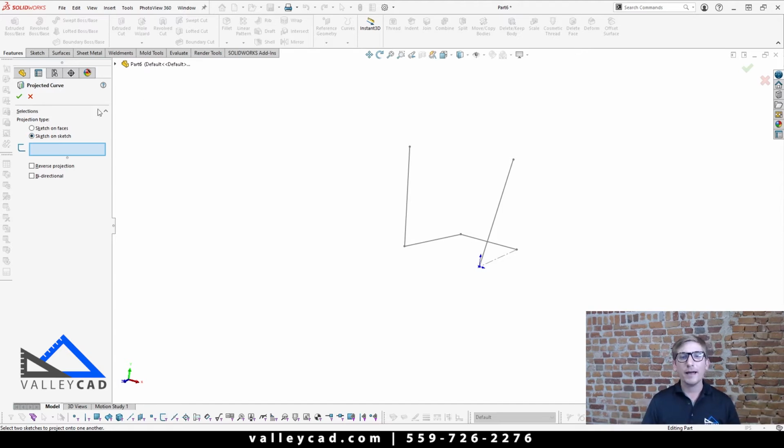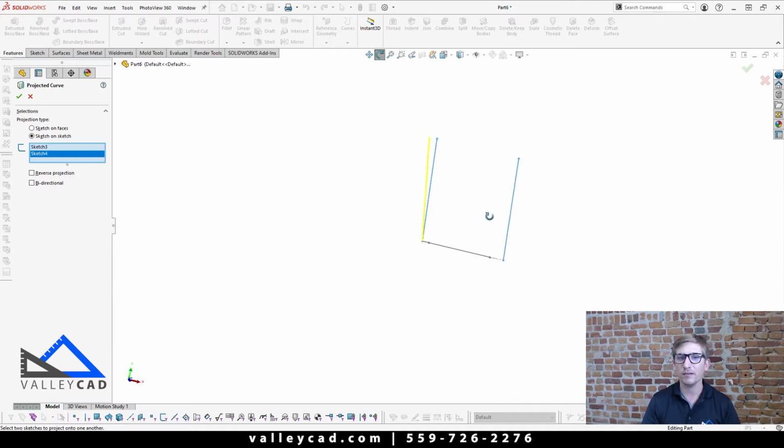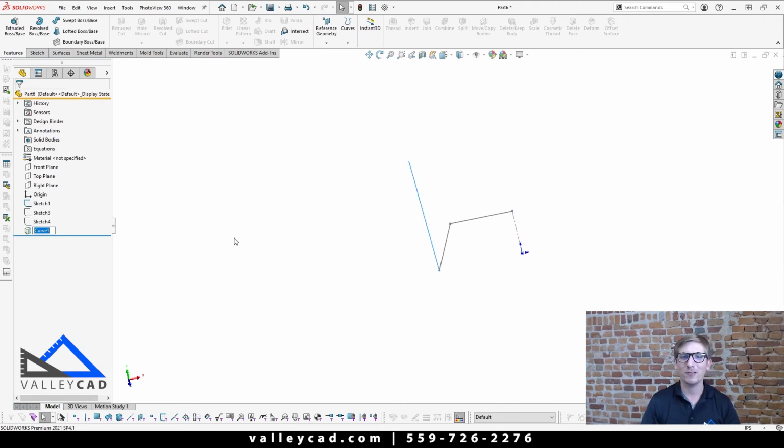And so this, if those of you that are familiar with the term Boolean, this is kind of that approach. So imagine that this sketch entity here is traveling perpendicular to the front plane, so it's going straight back. And in the other sketch that's coming off that 65 degrees, that's on my right plane, imagine that's being projected out this way. And so wherever they intersect will now make a new curve for me, a Boolean effect there. So from there and there, now we can see those 2 2D sketches being made into basically a 3D sketch from there. Say okay to that, and there is my new 3D kind of complex geometry.